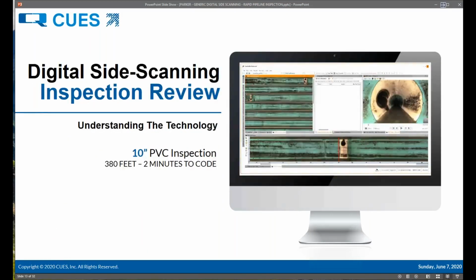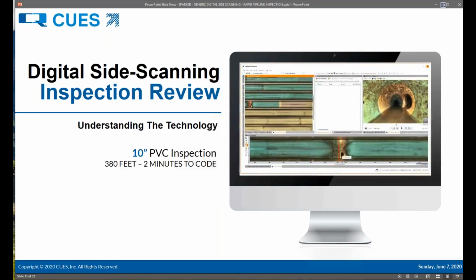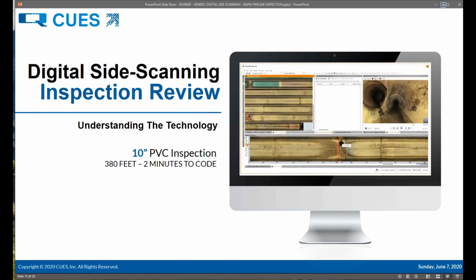So in this case, it's a full digital side scanning review as if we just started this pipe section. It's a 10-inch PVC pipe. It was 380 feet in length. Of course, PVC is not very eventful for the most part. So in this case, outside of 4 laterals to code, there were a few areas that had some staining that could be documented as potential infiltration. That was really all there was to code in this particular line segment.